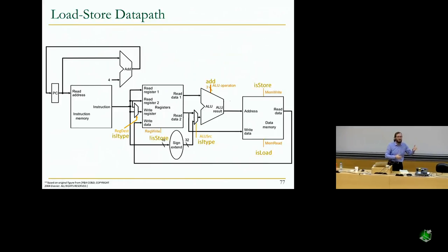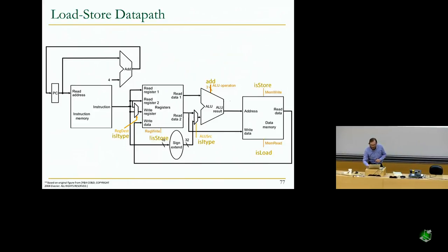For example, when you decode a store instruction, you set a bit, is this store? It's a store. And this could be directly connected to memwrite. Now you can think about how to generate the control logic also, right? Based on the decoding of the instruction.